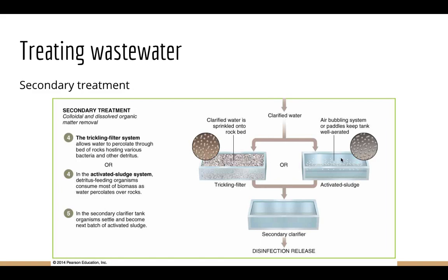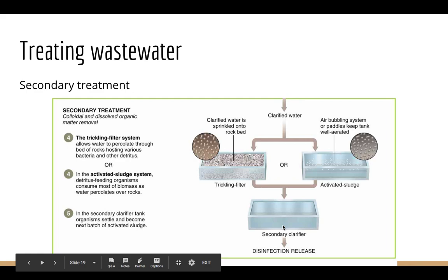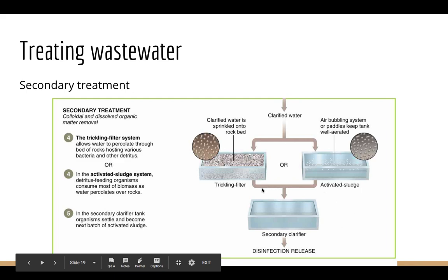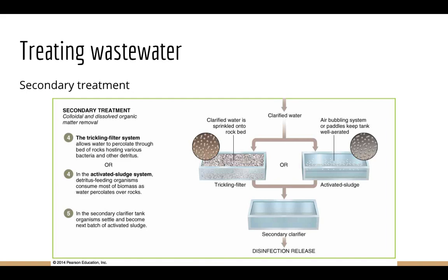And then the organisms and the wastewater end up in this secondary clarifier. The organisms kind of clump together, and they're going to settle out, and you're going to be left with water where all the waste has been broken down. So now you're just left with CO2 and maybe some mineral nutrients. At the end of the secondary clarifier, once the water is pumped out, at this point, 90% of the organic material has been removed. So not quite done yet.